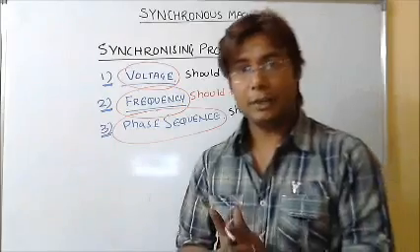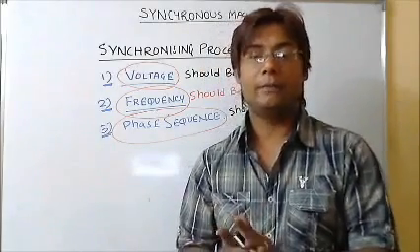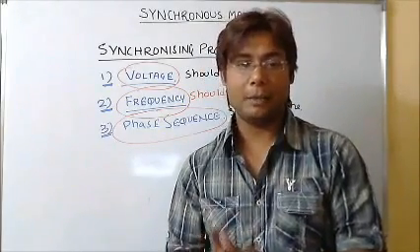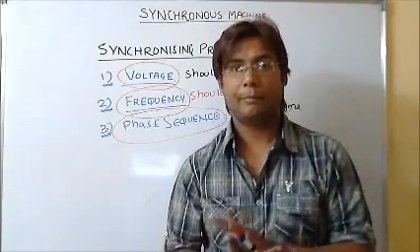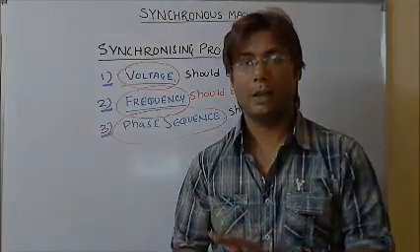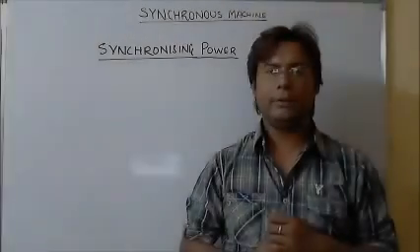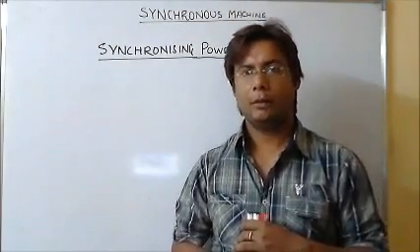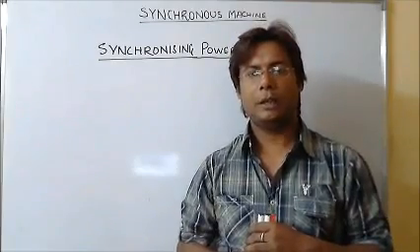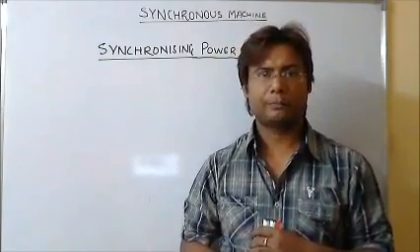At the instant of synchronizing, the voltage phasors of the generator and the bus bar must coincide. Otherwise, the synchronizing procedure will not happen. We will continue with synchronous machines with another very important phenomenon, the synchronizing power.